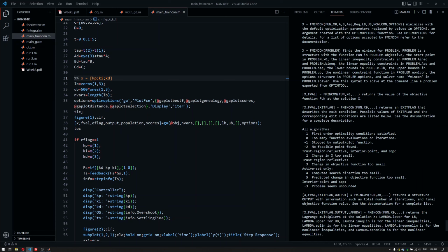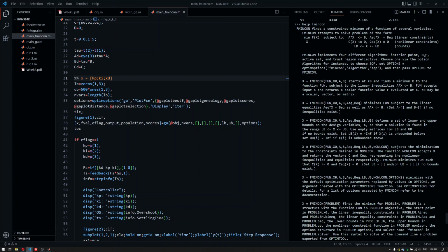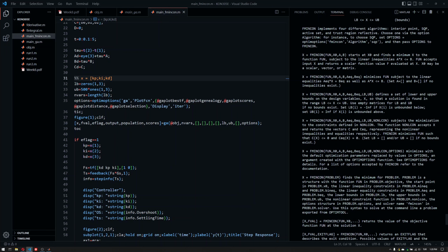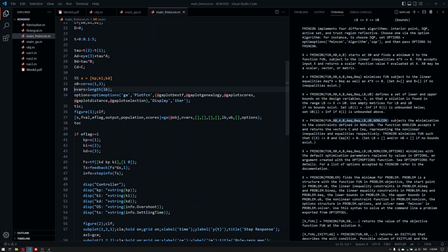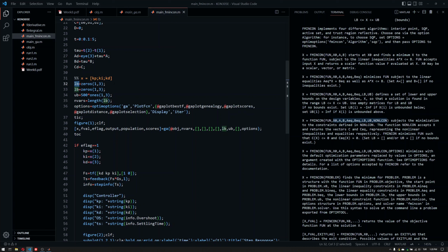We can look also for, it has kind of the same structure. You can see it is, again, an optimization tool. We can have an objective function here. It has some algorithms: interior point, SQP, trust region, active set, etc. It uses a bit different stuff here. This looks more familiar to us. We have x0, so I'm going to call it x0. Let's copy it, call it x0.